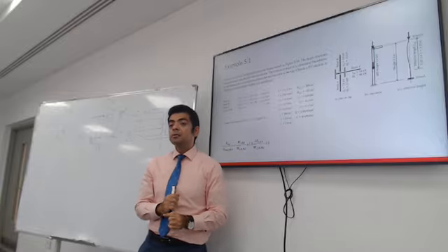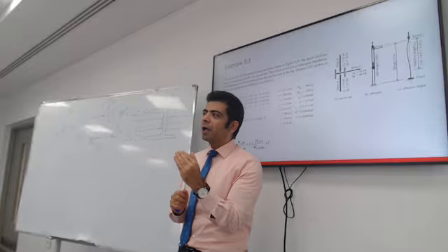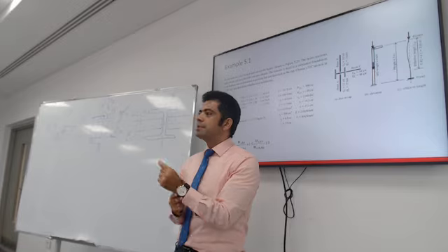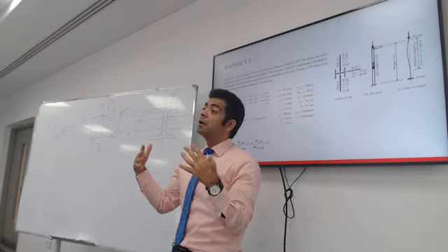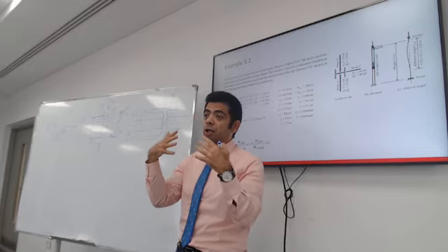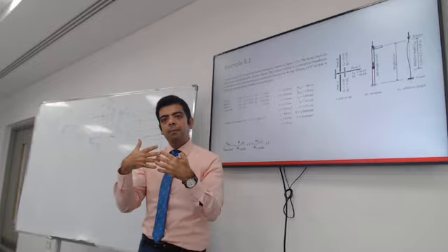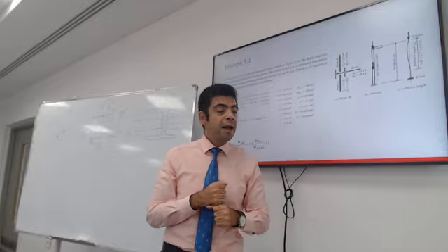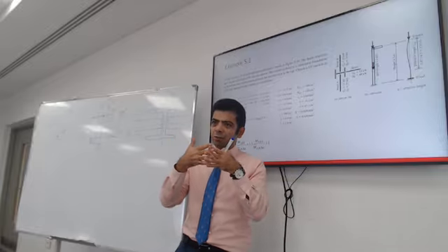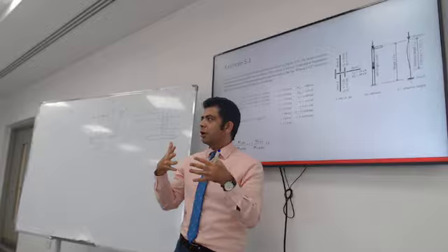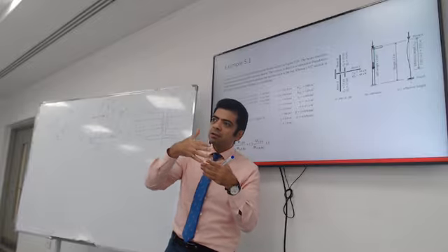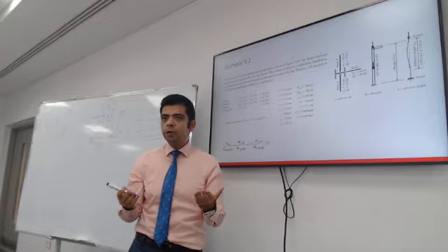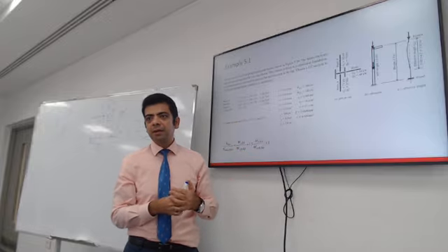At the same time, I don't like to push the efficiency to 0.999 because that usually doesn't leave enough space for the connections. The connections will take some of the geometry of the column, and they have their own capacity as well. So don't stress out the column or the beam too much, because when the designer comes to fit the connections, it's unsafe. So I would say 0.9, 0.85, that's reasonable.